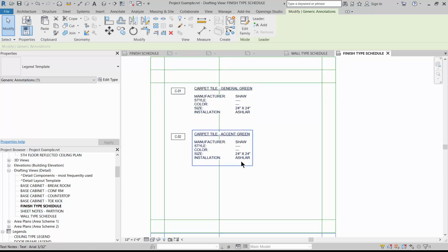And then if you have carpets, and then you have resilient, and then you have sealed concrete, again, sort them in subgroups. So your uniform sorting, where you place things in categories, is going to be a good guideline for specifying the exact specification and manufacturer callouts for all the finishes on your project. And then just pop it on a sheet when you're done.